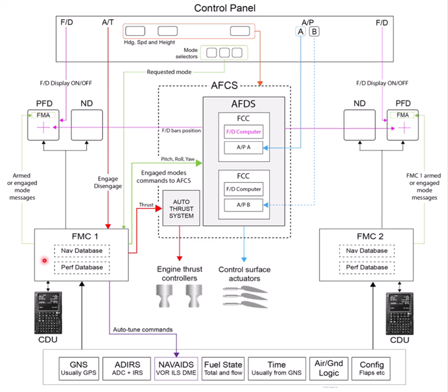So, by programming via the CDU, the human machine interface, by programming the FMC, giving it the information it needs, we've allowed the auto flight and control system, the auto thrust and autopilots, as long as we press the buttons telling them what we want, we've allowed that to fly the aircraft on a lateral and a vertical profile. Thrust is being dealt with automatically. Okay, there's nothing we need to do, and that's basically it.